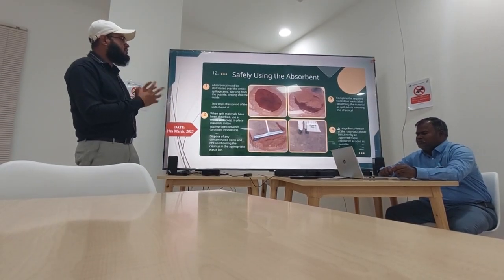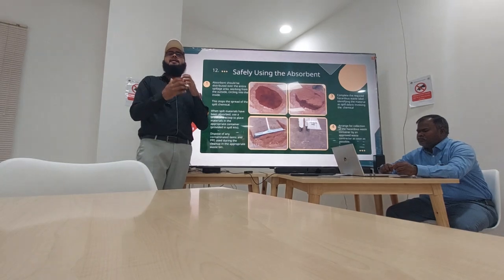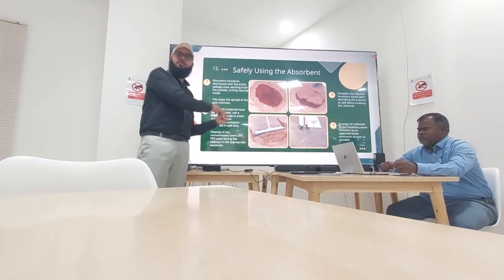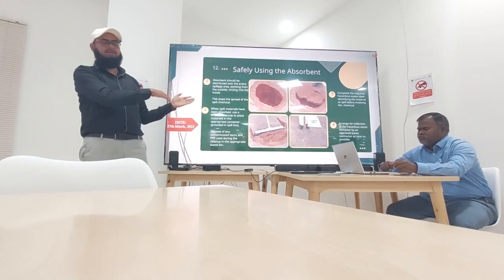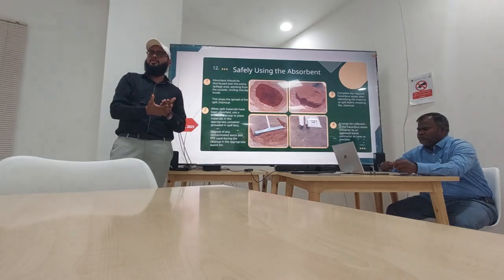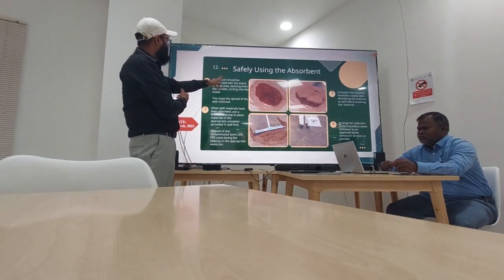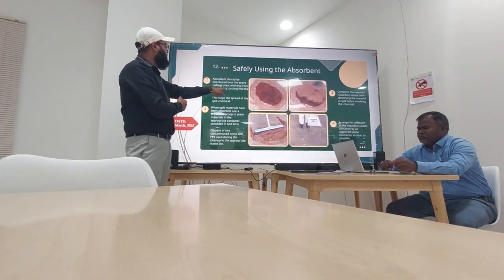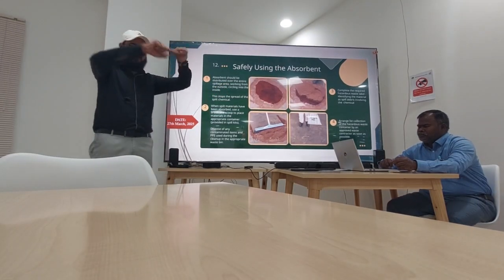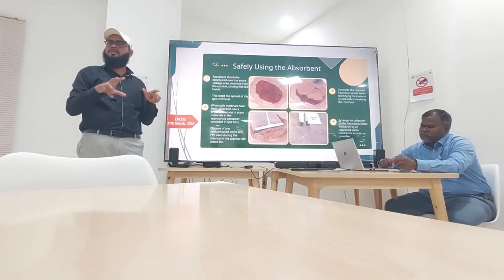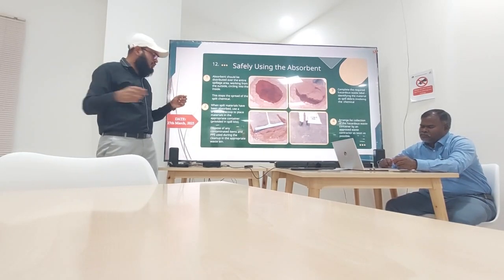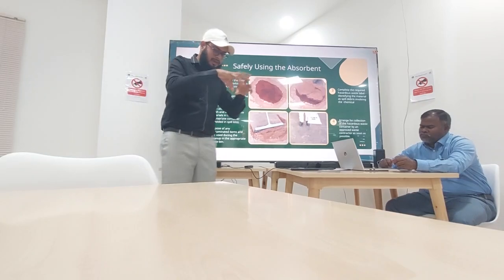So how can we use absorbents, and what is the cleanup process? I also have a video tutorial for better understanding after this. First, we will go through it one by one, then we will have a video representation. Absorbents should be distributed over the entire spillage area, working from the outside and circling inward. First, make a circle around the spillage so that it will not travel or spread further. Then make sure it is properly contained.